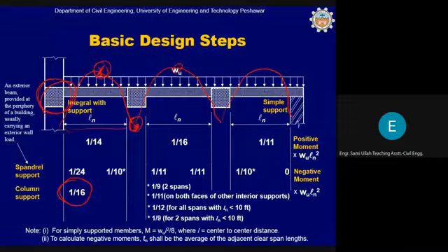And if you try yourself, develop several situations: a beam terminating into a beam, a beam into a column, a beam on the slab, okay, and assign these bending moments to the situation which you are considering. So it will make your understanding better in this approximate procedure for analysis. Okay, and if still you have any problem, you can ask questions. Okay, next. Any other question, please?